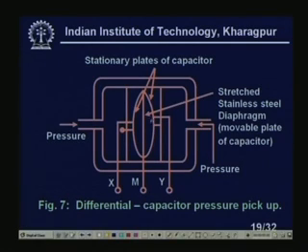You see here, this is our movable plate. It is moving in this direction or this direction. If this pressure is higher than this pressure, the diaphragm will be stretched in this direction. It will look like this. And if this pressure is higher, then the diaphragm will be stretched in this direction, right.